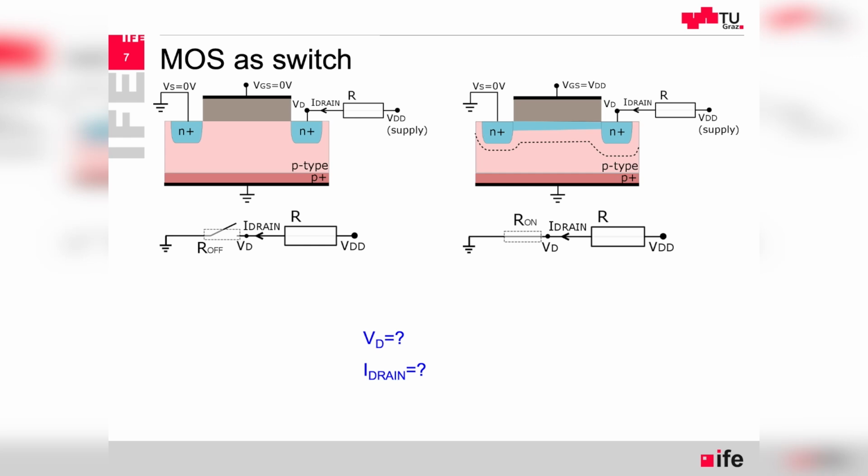So the characteristic of the material is N+ all along under the gate. So in fact, what we are doing is controlling the resistivity by applying voltage to the transistor.